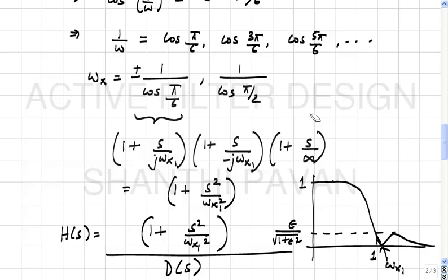So the next best thing is to say ellip, open bracket, 2 dB ripple in pass band, 40 dB attenuation in stop band, 5th order, close bracket, hit enter, and then MATLAB will give you all the polynomials. Of course you could have done all this even for the inverse Chebyshev and the Butterworth, but I thought it's fairly simple stuff, and you should have some idea of how all these things come about.